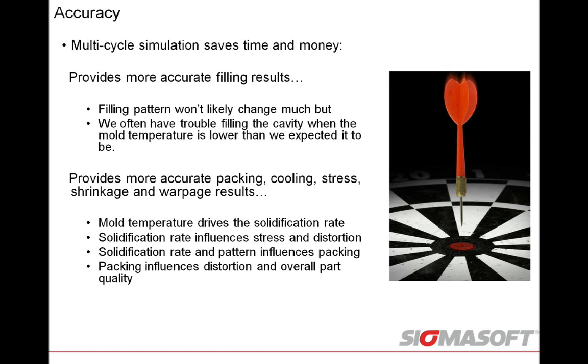This drives your solidification rate: how fast the part cools, how fast a semi-crystalline material crystallizes. And of course, that solidification rate is going to influence your stress in the part and your distortion of the part. It's also going to influence your packing rate, and as we know, packing influences distortion as well and overall part quality.